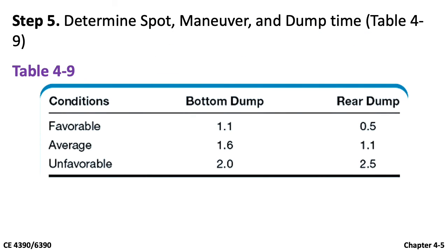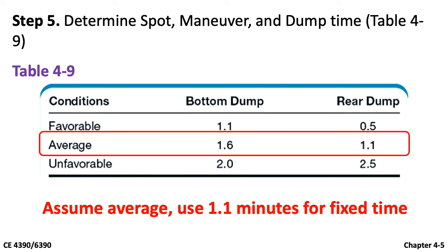Step number 5, determine spot, maneuver and dumping time. So you can use table 49 to calculate total of all the fixed time. So assume the average condition in given real dump trucks. So we use 1.1 minutes for the total fixed time.